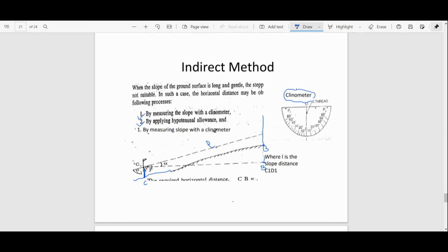Now we have to calculate theta. At this point we lay down the tripod stand and fix this instrument, the clinometer. This clinometer has a telescope, or a cross here. We just look through this until this point is seen. Okay. Now we calculate the angle from the baseline, how much angle it has. Now simple, we have to use a geometry concept here.